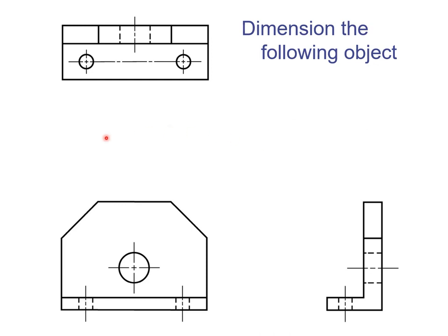Let's identify our datums. So a good datum is the base. This can be one of our datums. We can actually consider the back surface our primary datum because there's more surface area than the base. But maybe it was manufactured with this mating up to the 3-axis table. Okay, so this is a good datum. This is a good datum here.